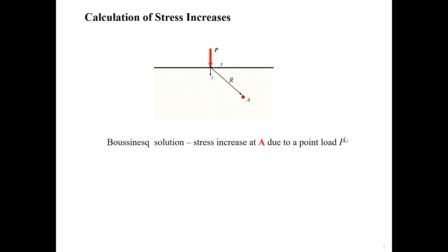The engineers would like to use the stresses based on elastic theory because they are closed form solutions. That means we can get a very simple equation that you can just program into a spreadsheet or a MATLAB program. These solutions tend to be conservative for most cases, meaning they are not going to underpredict the stresses.